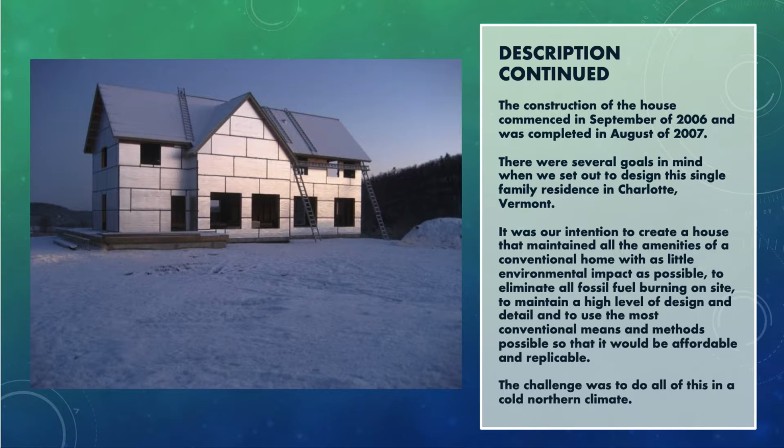Okay, so the construction of the house started in September of 2006 and finished 11 months later. Depending on your project, that's interesting. They were building with snow on the ground. It's hard to do that, so you want to make sure you do all your site prep before it's going to get cold enough, because the ground freezes in Vermont.